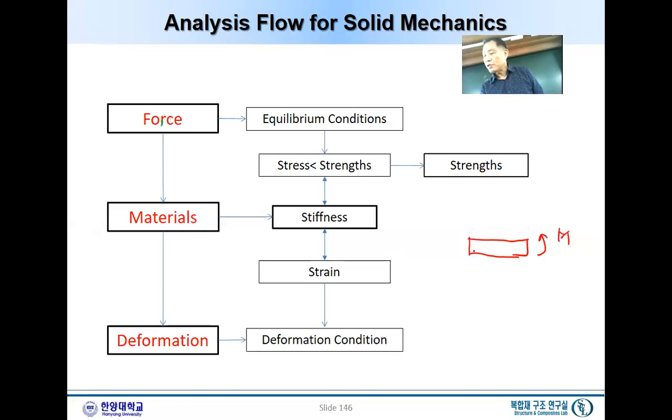We just focus on just one beam, and the beam supports a moment at each end, or this is equal to a fixed end, and here same L, and apply a moment. So for this reaction force to be in equilibrium, we will have this moment. So this one and that is the same thing, right? So just a fixed end and you apply a moment.